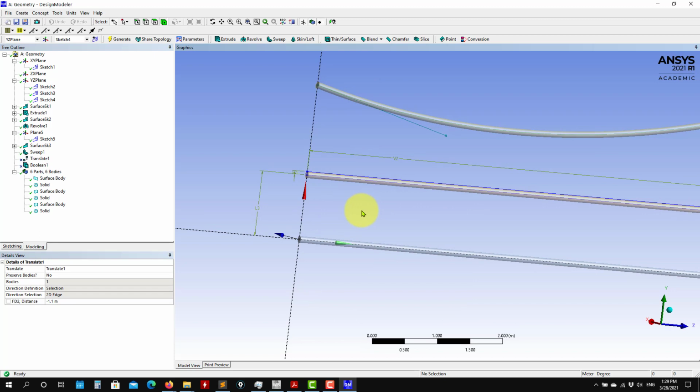So what you see here, everything that we have done is parametric. If I change something, everything will update. This is very important when you are creating parametric CAD. Think about the parameterization, because you want to update everything in a few quick operations, not by changing parameters one by one. As you have seen, there is no single way to do a geometry. It's up to you how to choose, but usually it's a good idea to take the easiest one. For instance, in this case, it might be this one: create the circle and extrude. And think also about the parameterization. So it's up to you.